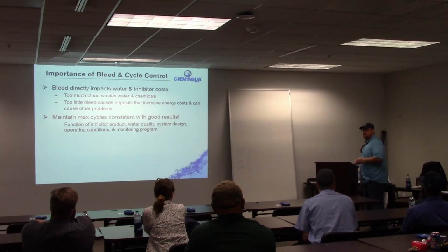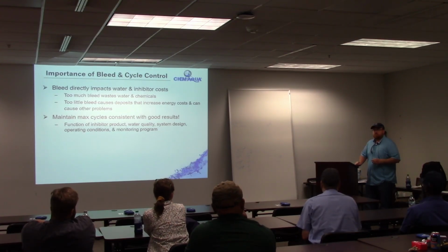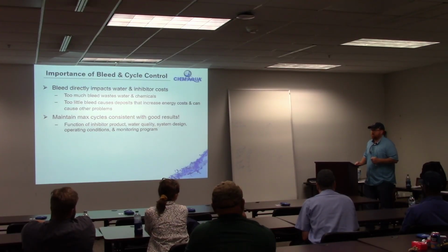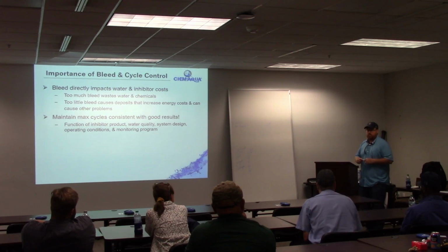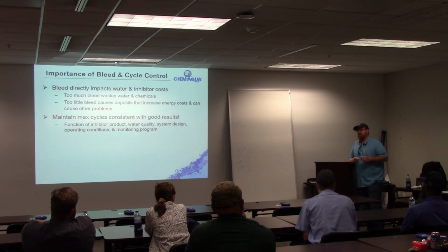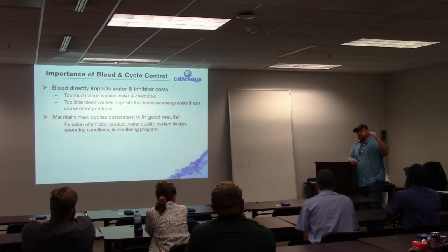So that's how we maintain that set point. So in summer, is it common to have it blowing down constantly? It can be. You have a higher heat load, and so your evaporation rate's a lot higher in the summer. You don't have free cooling. You're having to cool the water, so your fan speed is probably running all out during the summer, right? And because you have that accelerated evaporation rate, your mineral content in the water is concentrating at a higher rate.